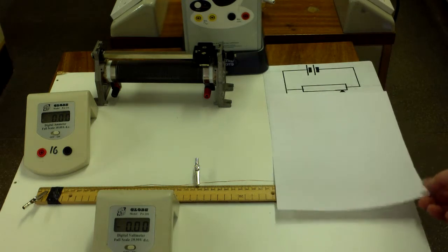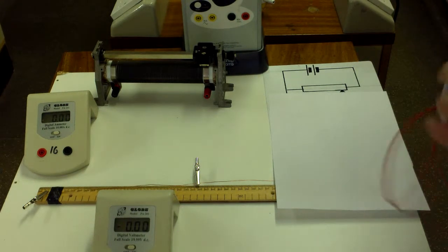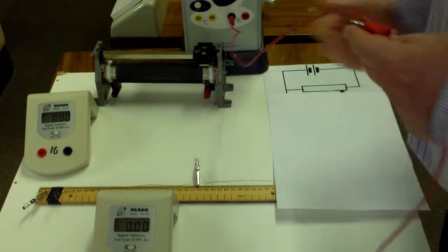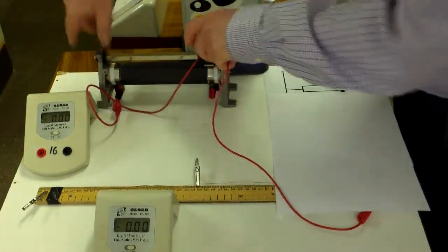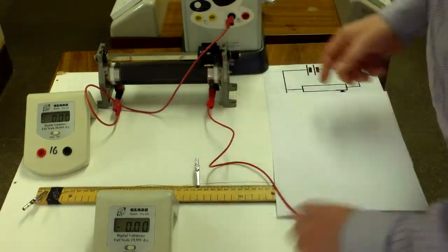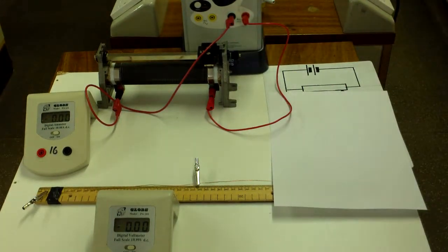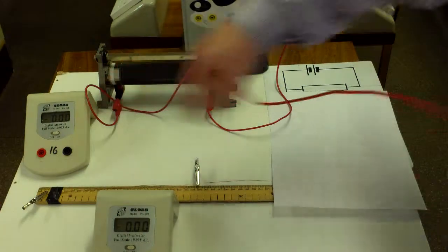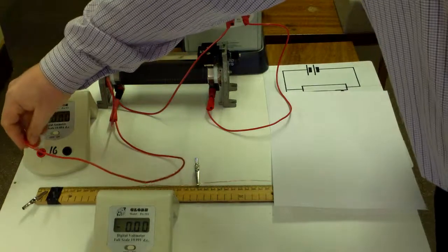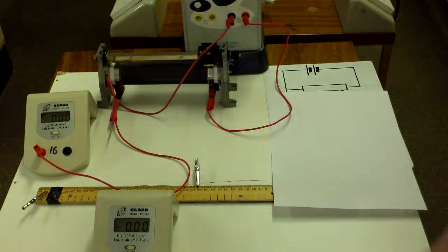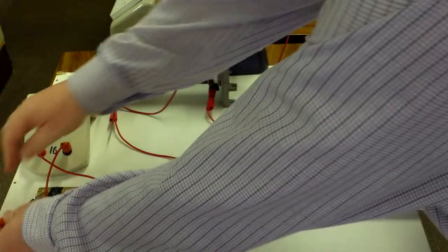So the first thing that I do is I connect a type of resistor called a rheostat to the power supply. So I put two wires into the red and black holes on my power supply, and they go to the bottom terminals on my rheostat. I then connect the rheostat to the ammeter. Again, I use one of the terminals at the bottom of the rheostat and I connect that to the ammeter. And then in series with the ammeter, I connect my wire, which is on a ruler, so I can measure the length.